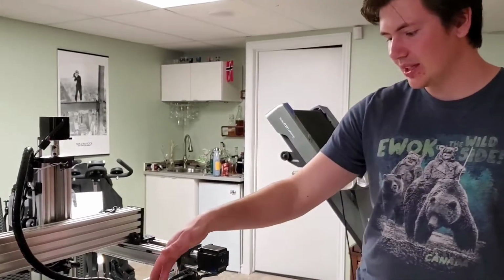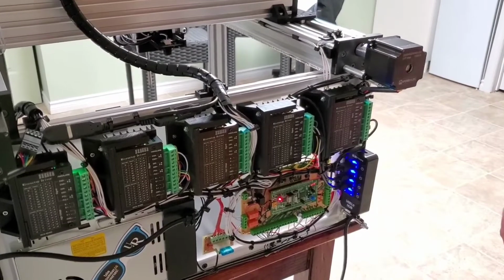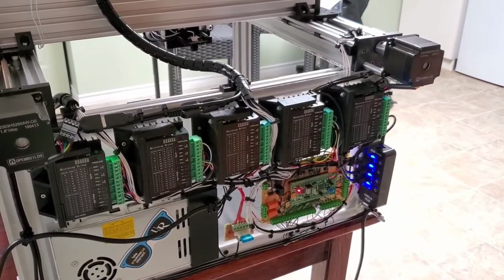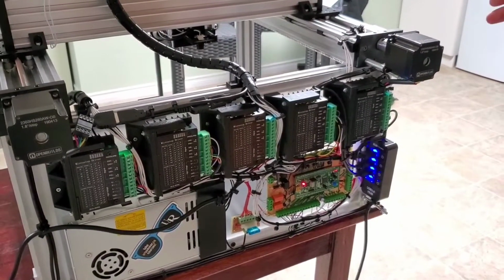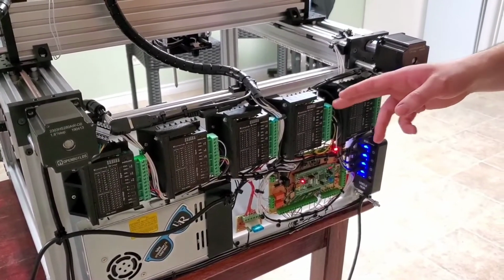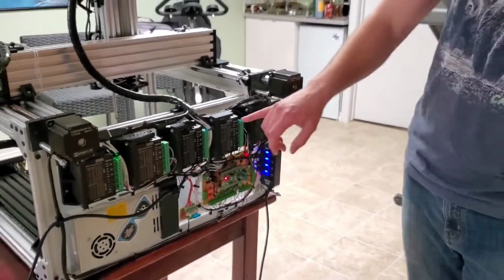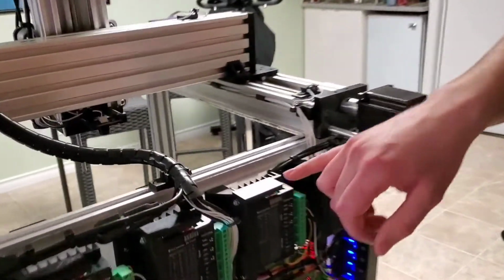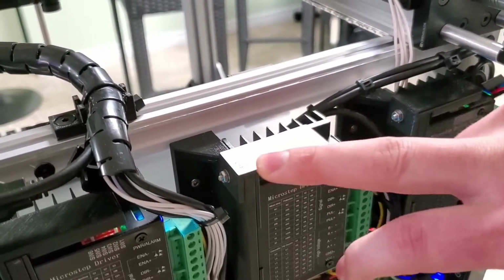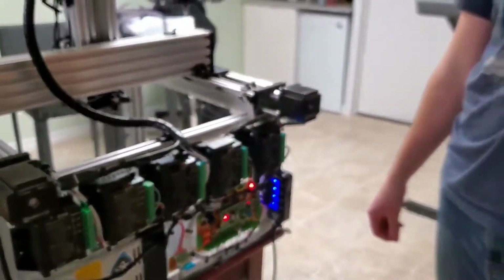So we ended up selecting the TB6600s. These are a relatively low-cost stepper driver, which was good for us. They have micro-stepping down to 1/16. We only end up using 1/4 micro-stepping, but it has the ability to go more precise. They support up to 3.5 amps, which was more than enough for our stepper motors. At the top here, it's very easy to adjust with just a few little switches, and we actually 3D printed these covers to prevent anyone from flicking these switches once the settings are dialed in.